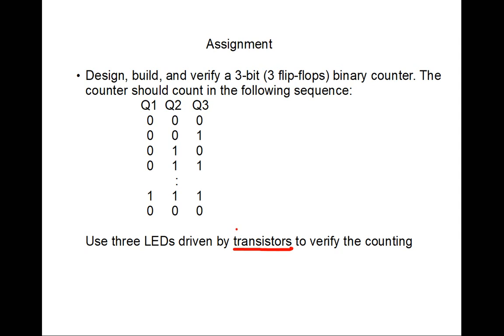You can use transistors, or if you wanted to, you could use an inverter here. I can go either way on that. What we do is put an inverter, and then we put our LED, and then a resistor to ground. Again, this inverter would buffer the LED a little bit for us. But I think the easiest way is just to put the transistors.